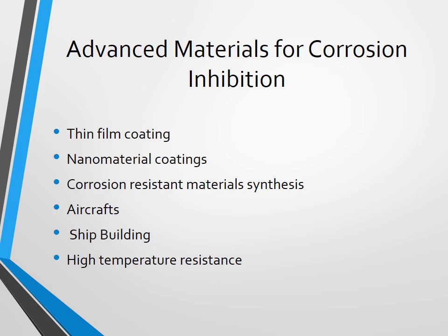So to avoid their corrosion, we will use advanced materials which help them to avoid the corrosion process, and we can do it by sacrificial coatings or galvanizing or by painting the surface of the materials. In aircraft, that also includes some strength in addition to preventing corrosion, and advanced materials help with this corrosion and also provide strength.